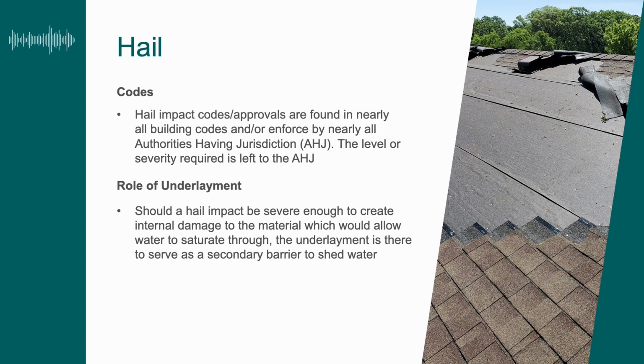If you're doing work in an area that you're unfamiliar with, make sure they don't have some particular weird code. An example: in Florida, Charlotte County is kind of up there in the middle of nowhere, and for years that building official has come across with the most bizarre requirements at times. He'll suddenly want something from a hurricane zone where it's not required by Florida's code. You just need to make sure you know what you're dealing with, so you don't get into a contract, get a job done, and then find out something weird goes on.